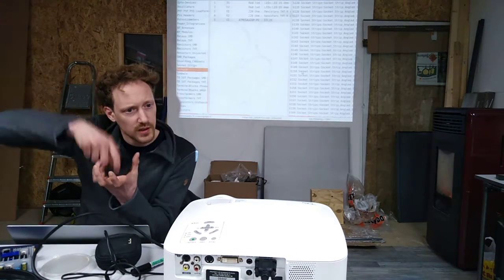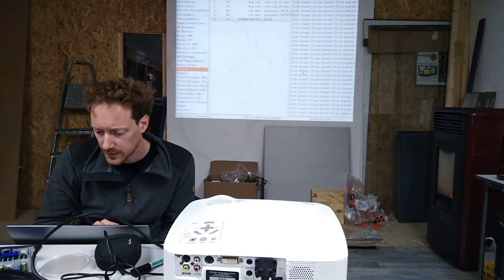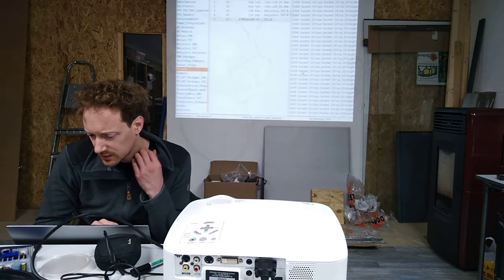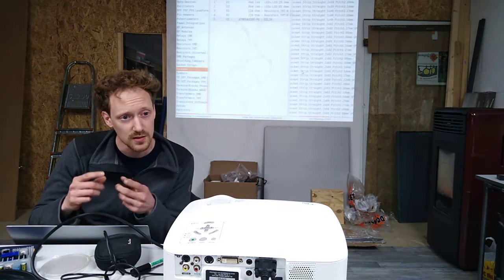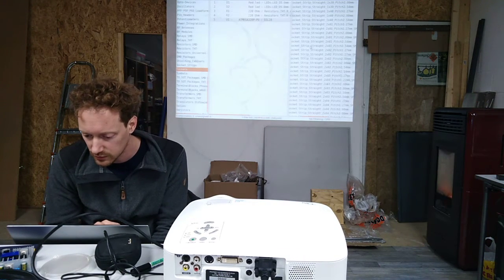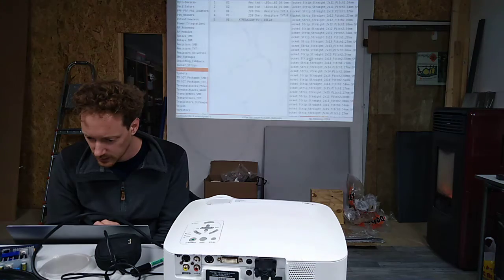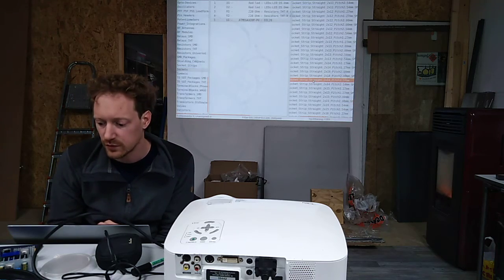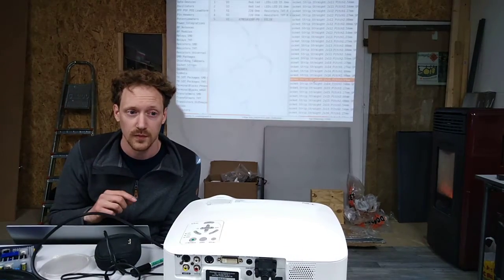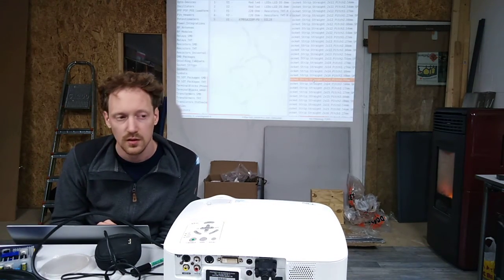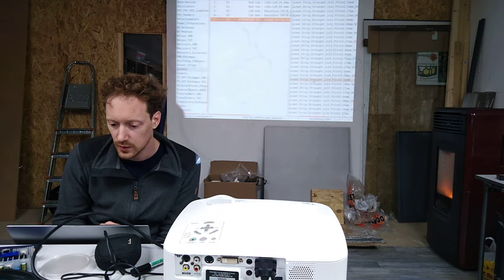So this is a socket where you can put a 28-pin thing in. We want to have the straight ones of 2 by 14, because we have 28 pins arranged in 14 on the one side and 14 on the other side. So we're going to choose 2 times 14, and with, I believe, a pitch of 2.54 millimeters. I think that's the breadboard. Or? Yeah, I think that's what the breadboard uses. 1/10 of an inch. 1/10 of an inch, indeed. So we're going to assign that.